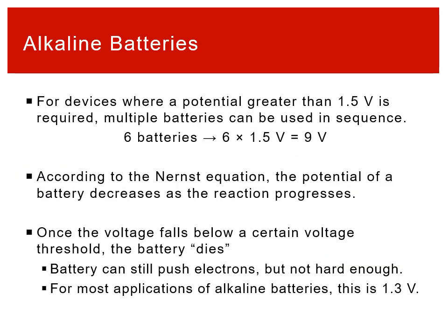So a lot of times the 1.5 volts of a cell isn't enough. How you actually get more potential or more voltage is you just put multiple batteries together in a sequence. That's why you potentially need to use multiple batteries in, say, a device. Sometimes they're also packaged as a product as it is. For example, if you buy a 9-volt battery, that is basically 6 smaller batteries put together in sequence, or in series, to use the technical term. You do 6 of them, that multiplies the potential, and you get 9 volts. So that's how you drive a 9 volt.